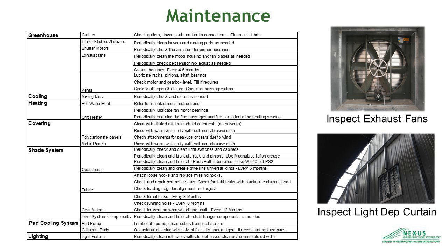So the next question we get asked is, how much maintenance do these greenhouses take? And for the structure themselves, it's actually relatively simple. There's not much maintenance involved at all. Getting up and cleaning the gutters is one of the biggest pieces of work that you have to do for the greenhouses. And if you occasionally look at your cooling system, the different items you have to look at in your cooling system are your intake shutters. You'll have to occasionally clean those. Your shutter motors, you'll have to occasionally clean those and grease them as well.